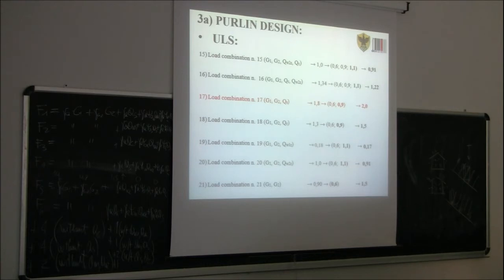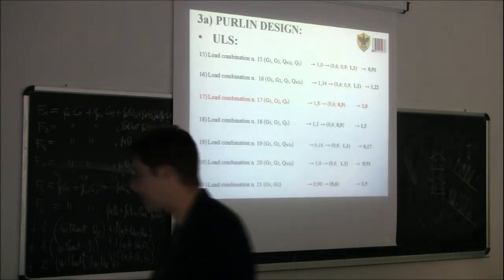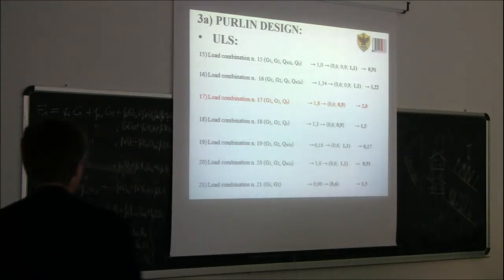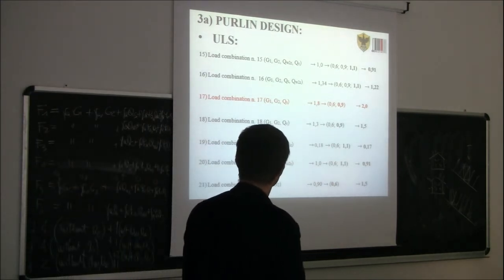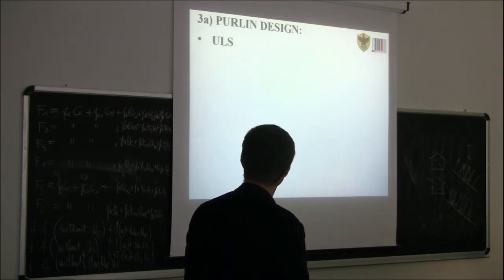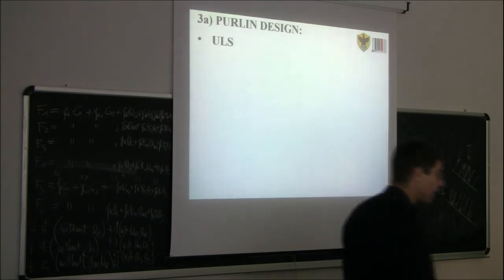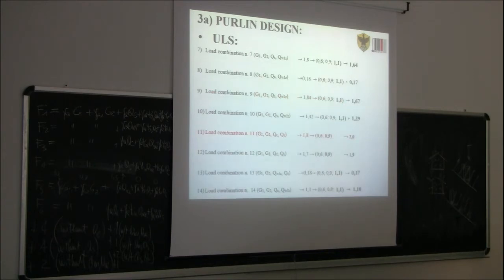So, despite those load conditions not being the maximum ones, so the ones with the maximum value, those are the most critical ones because the k_mod here is lower. So this means that from here we have to continue in our design by using only load combination number 17 or load combination number 11, because they both have the same value.